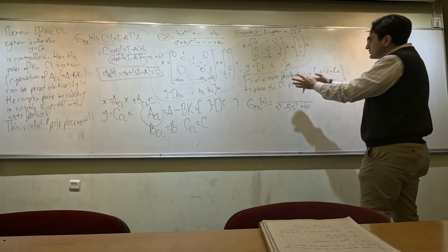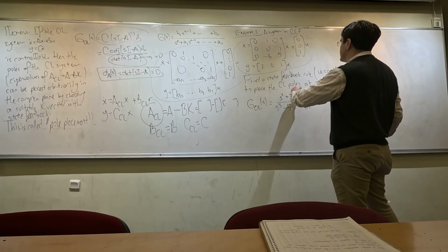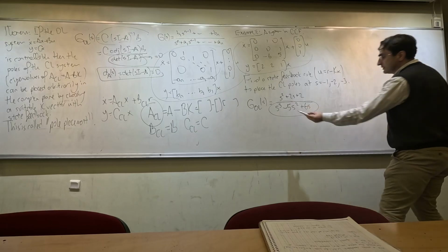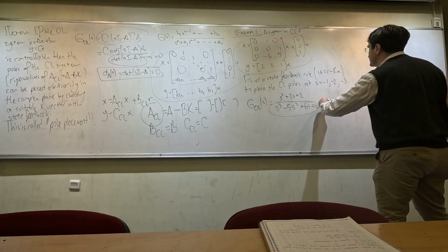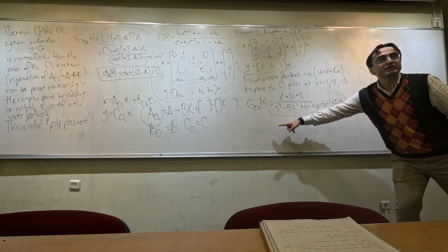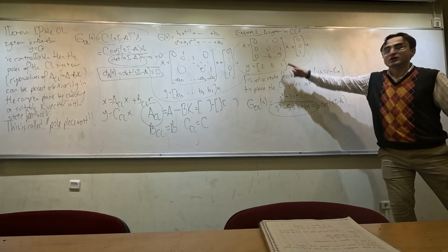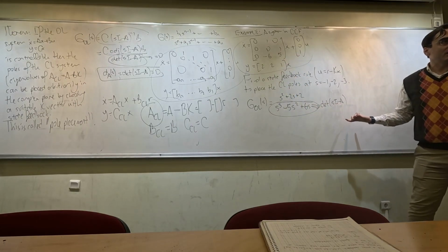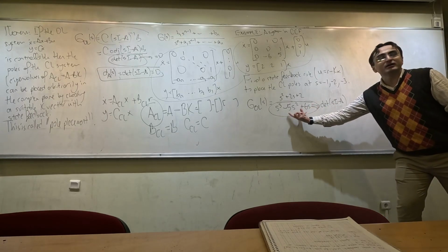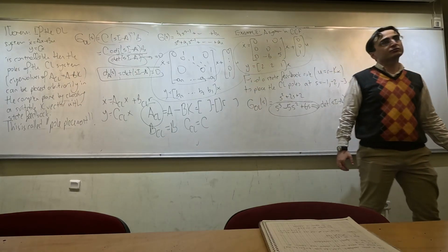And then I can write what the numerator is. It is going to be s squared plus 2s plus 2. Okay? So what is this denominator? This is the determinant of sI minus A itself. It is the characteristic polynomial of this A matrix. I didn't calculate sI minus A, I didn't calculate the determinant, but I could write the characteristic polynomial of that matrix by looking at only its last row.